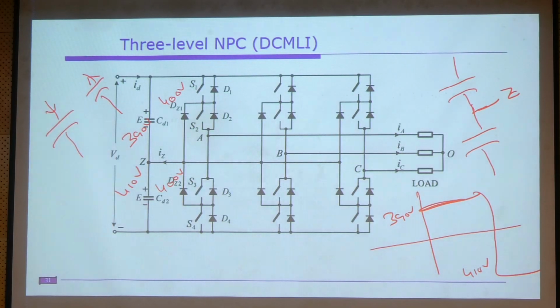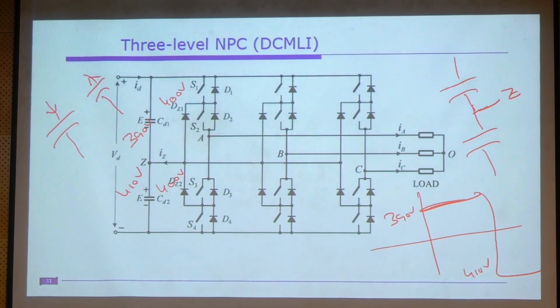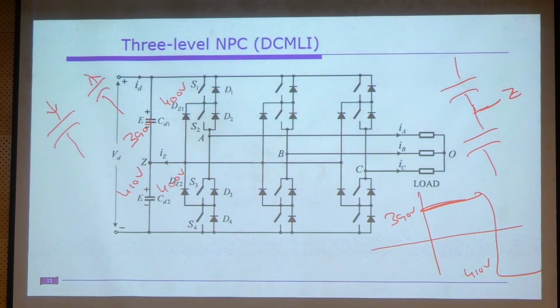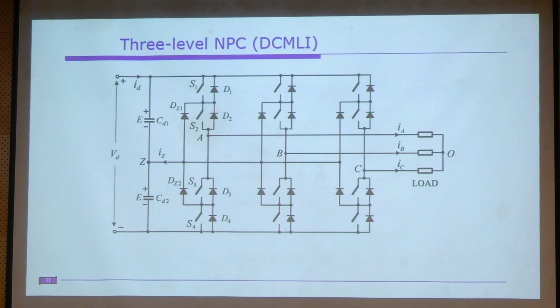Another commonly used method is model predictive control. By using model predictive control algorithms, we can feed one constraint to the controller, and so minimize the deviation in the capacitor voltages. Right, so this you are supposed to solve. Otherwise, there will be a large deviation in the capacitor voltages, and if the capacitor voltages are deviated, the entire operation will be disturbed.